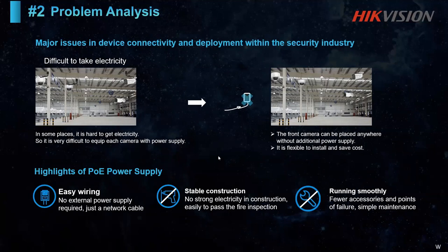So there will be no hassle to lay two cables, and the cost will be considerably different, considering the material and brand you are using. It may be higher or lower, it depends, and it will be easy to install as well, because if you are using an external power supply, you must get the power near the CCTV camera and you have to install a separate power supply there, and if it is an outside camera, you also have to think about waterproofing these power supplies as well. So it will be a really easy operation if you use this PoE function.